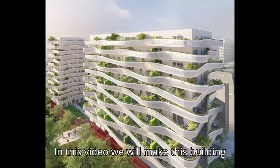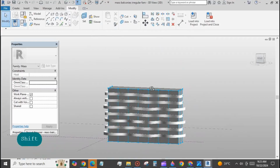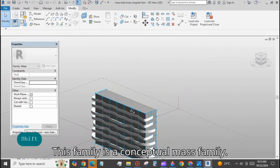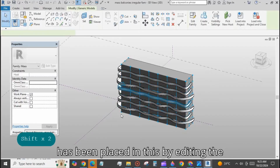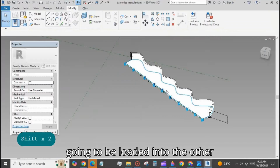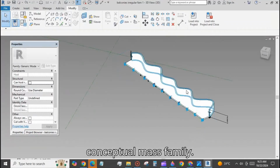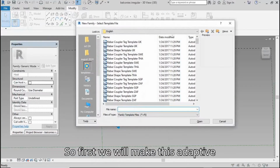In this video we will make this building that has balconies with irregular widths all around it. This family is a conceptual mass family. We can open the adaptive component that has been placed in this by editing the family. This is the adaptive type family and is going to be loaded into the other conceptual mass family. So first we will make this adaptive family.